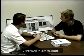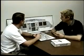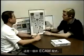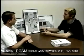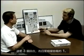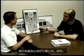Let's assume that the green hydraulic system failed and the landing gear is up. How can we extend the gear? And is this an ECAM procedure or a non-ECAM? This is a non-ECAM procedure. You'll get a note in the ECAM on the hydraulic failure to say you'll have to manually extend the gear, but the procedure itself is in the irregular section. To do that, basically you're going to have to crank the gear down. It's 3 turns and it's a pretty easy one. I don't even know what each turn does, I just know that I got to crank it 3 times.